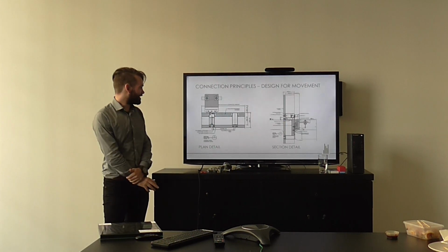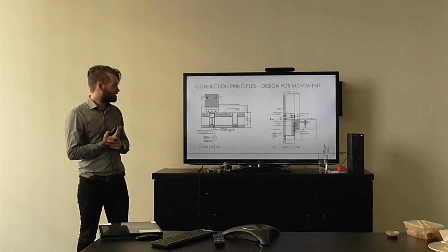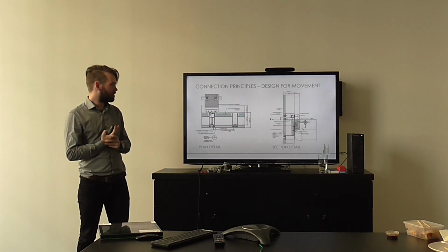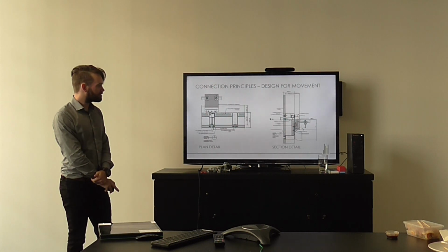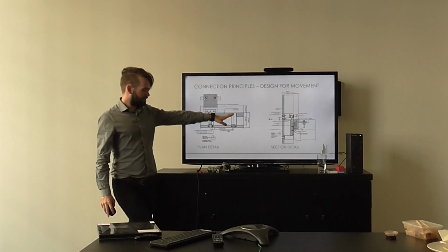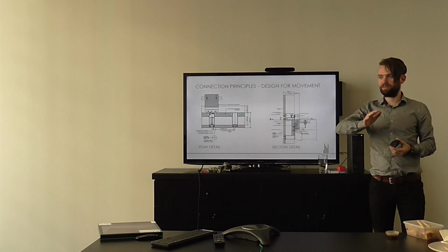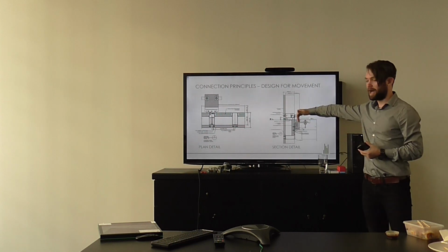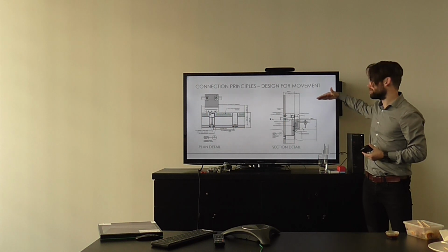We'll get to that. So I'm just taking the example here of a standard curtain wall bracket. Now, with this bracket, it has been designed for dealing with some of that building tolerance, but what we really need to look at here is this slab edge, which can vary quite significantly depending on where it is. So it could either be out, it could be in, it could be further down than we thought, it could be further up than we thought.